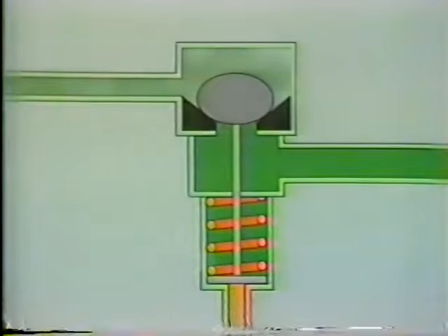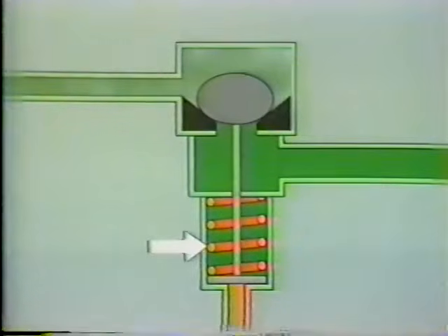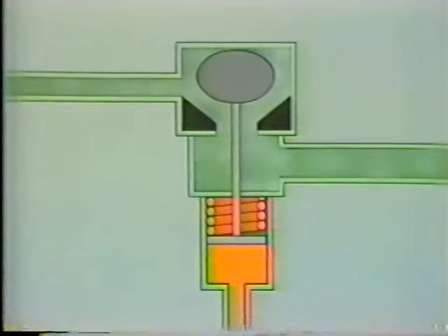The hydraulic actuator has a piston that's acted upon by hydraulic oil and a compression spring. During normal operation, the valve is held fully open. It's opened and held open by hydraulic oil pressure on the piston. The piston compresses the spring and pushes the valve stem. The stem lifts the valve disc off its seat. In this position, steam flows toward the high-pressure turbine.